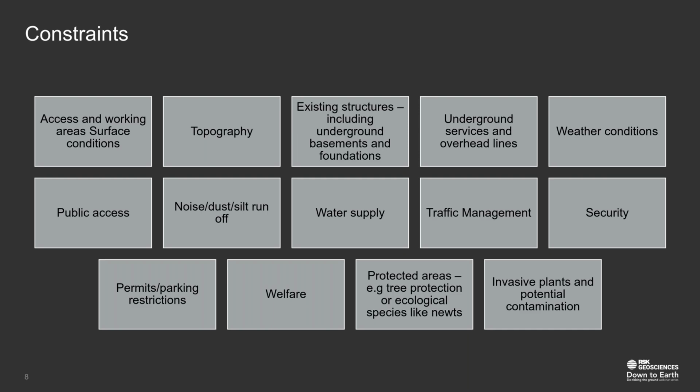Is there any public access? So is there any footpaths crossing your site, or any public access that you need to add additional barriers for? Do you need to consider noise? Is there people nearby, or a school? Do you need to consider dust or silt runoff?